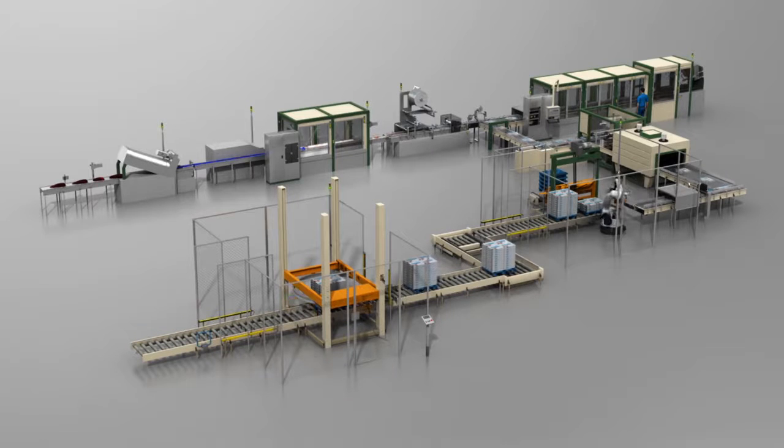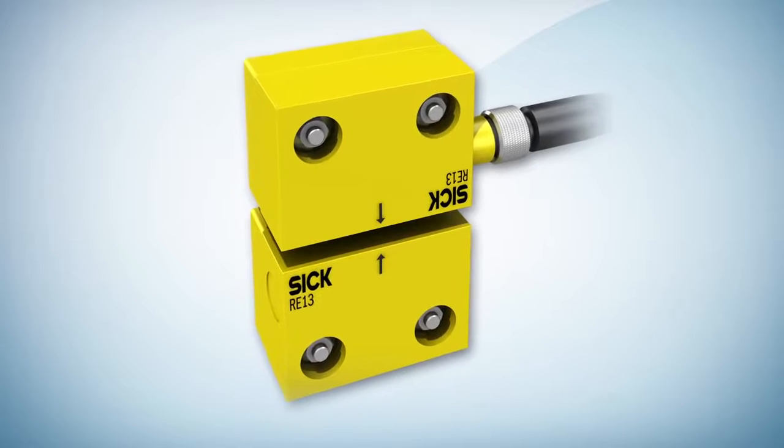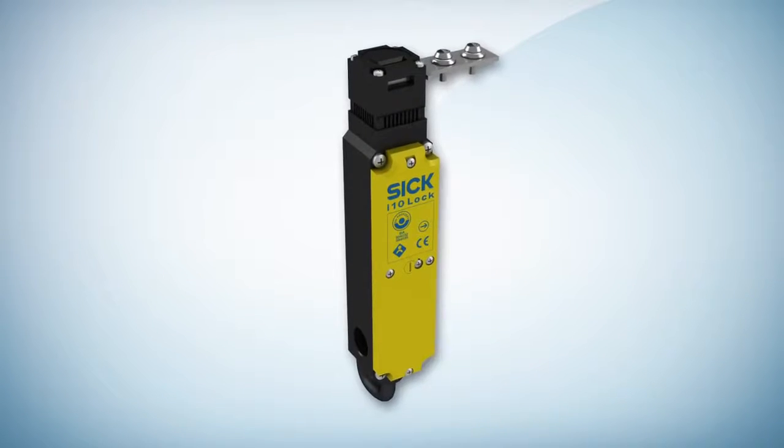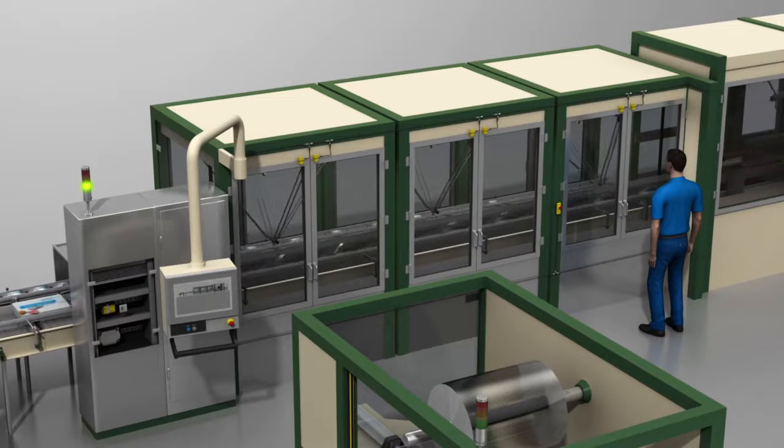Fault masking can occur in a series connection of switches with volt-free contacts, independent of their manufacturer. These include non-contact magnetic safety switches, electromechanical safety switches, and safety locking devices. To see how fault masking occurs, let's have a closer look at a packaging machine.